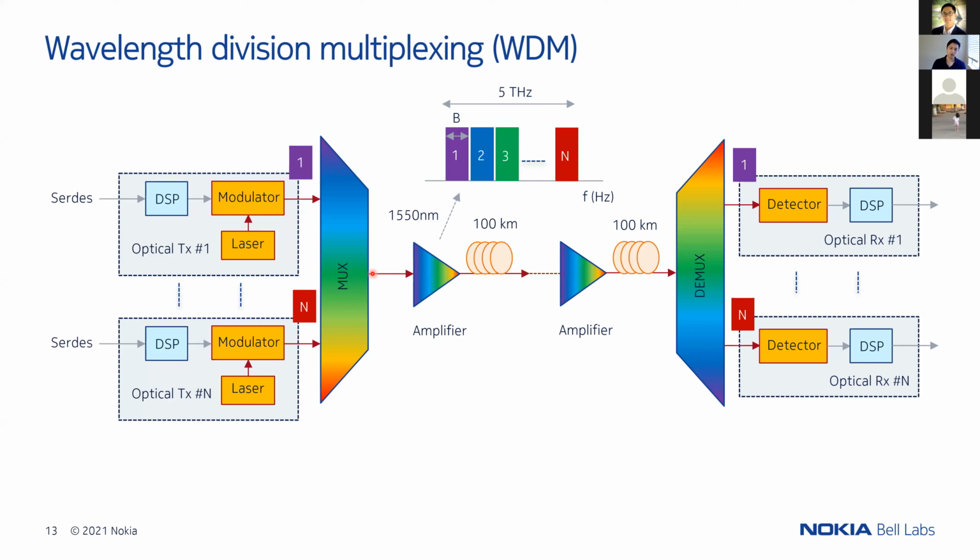And because optical communication can be used for long distance transmission, over 100 kilometers and so on, we need to amplify the signal because attenuation is still getting too high. And the most efficient amplifier operating in the C-band provides around 5 terahertz of bandwidth. So the availability of the amplifier defines the transmission scheme, right? Because we have an amplifier that provides 5 terahertz of bandwidth, and this is how the system is built today.